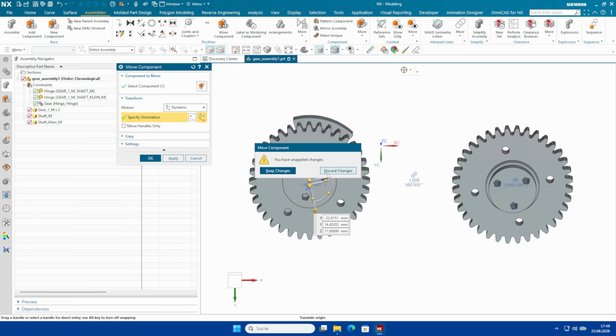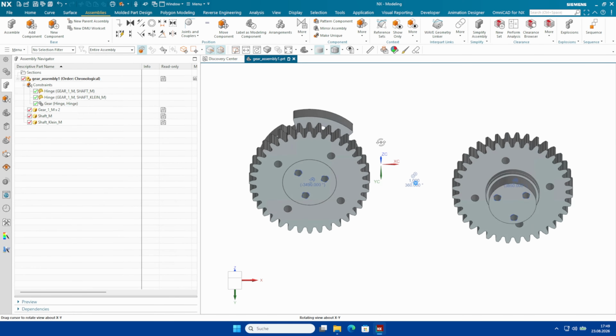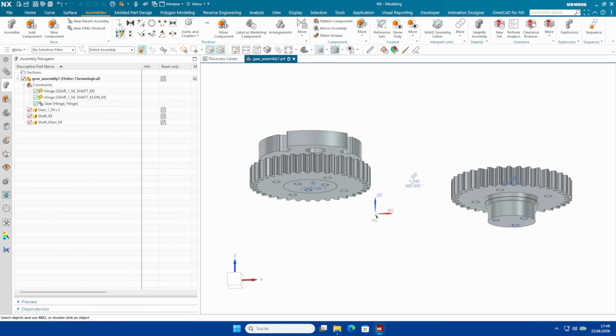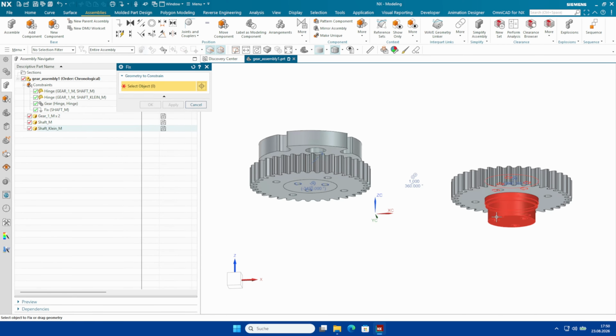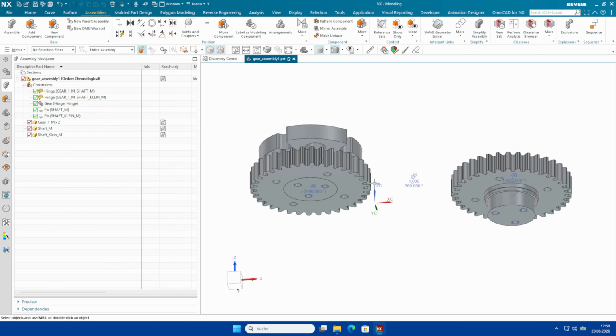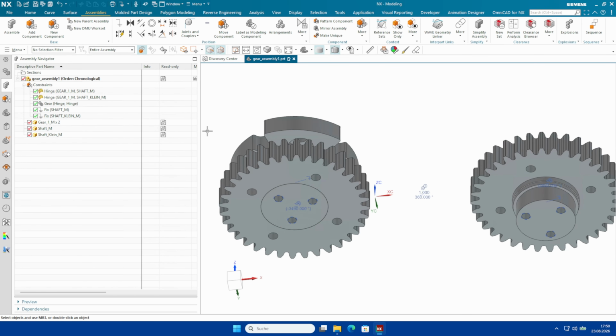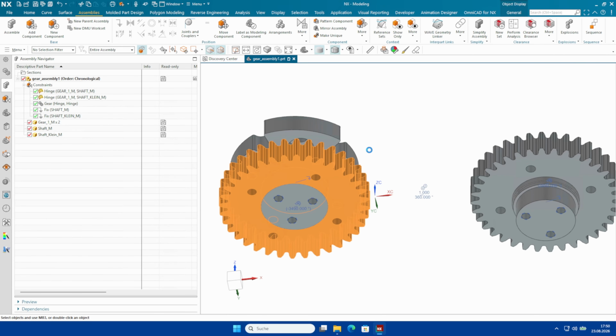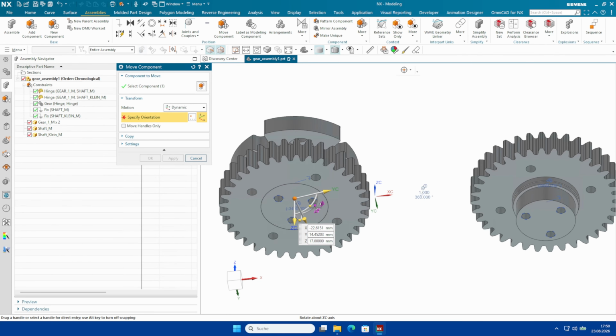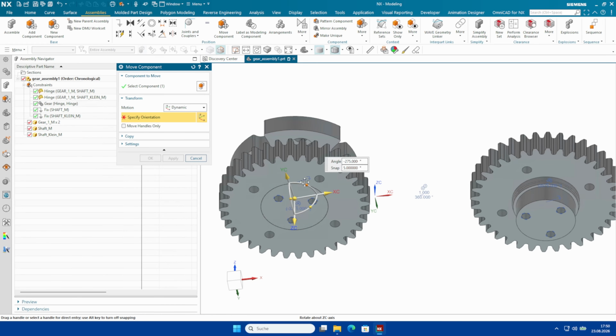So what I'm going to do is constrain my shafts as fixed. So I will fix my shafts so they will never rotate or move. So they are fully fixed. They cannot be rotated or moved. So now I will see if something changes. Yes, that solves the problem.